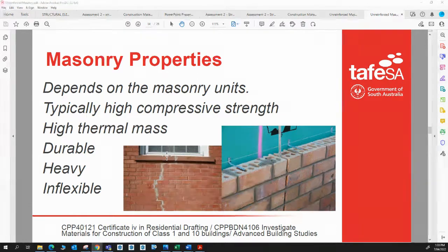But when you get shearing directly through bricks, so we see this brick sheared through directly, that one sheared through directly, also this one here, that indicates to me that there's quite a concentration of forces happening in that wall, that we've possibly got both expansion and subsidence happening very close to each other. Whereas diagonal cracking is typically more indicative of not a concentration of forces, so to speak.